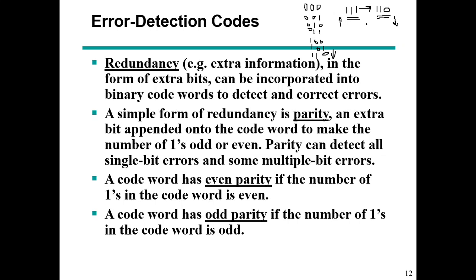So how do you counter such a situation? You can counter such a situation by using redundancy. Redundancy means using extra bits. There should be invalid codes. Okay? And you add another extra bit, say for example. Okay? So you add an extra bit.